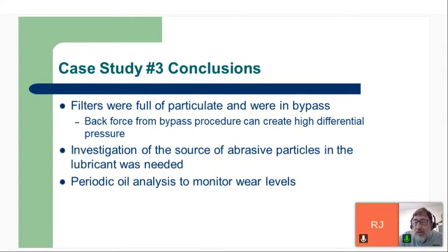More than anything, basically the customer was able to find out things about abnormal operation of the system by looking at the filter analysis. So, we think about what filter analysis is for. It's to find the dirt particles that the filter picked up. Yes, it can do that. It can also pick up abnormal wear conditions. It can compress the timeline, and look at things that may not be in the oil sample today, but did show up.